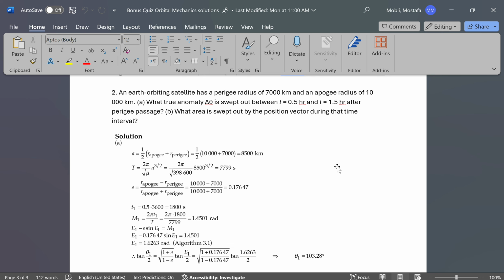Right now we are given a t, so we have to calculate the mean anomaly of the orbit. What is the equation for mean anomaly of the orbit? Go back to your notes, tell me what the equation is. Yes. M_e equals 2 pi over T times t. 2 pi over the period, times time. Time over period. Yes, thank you.